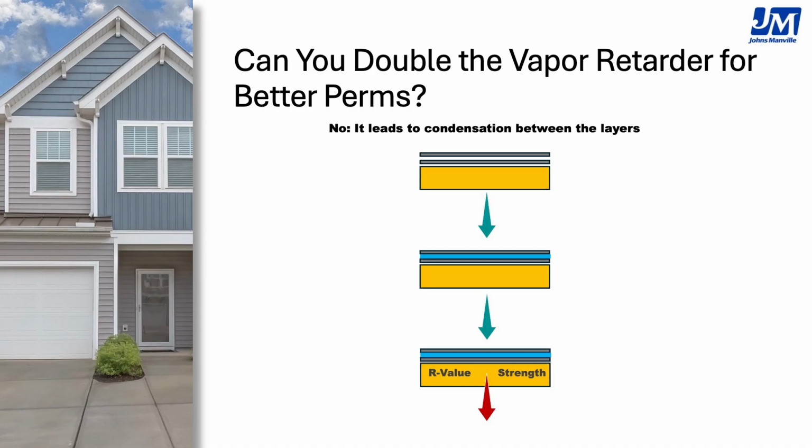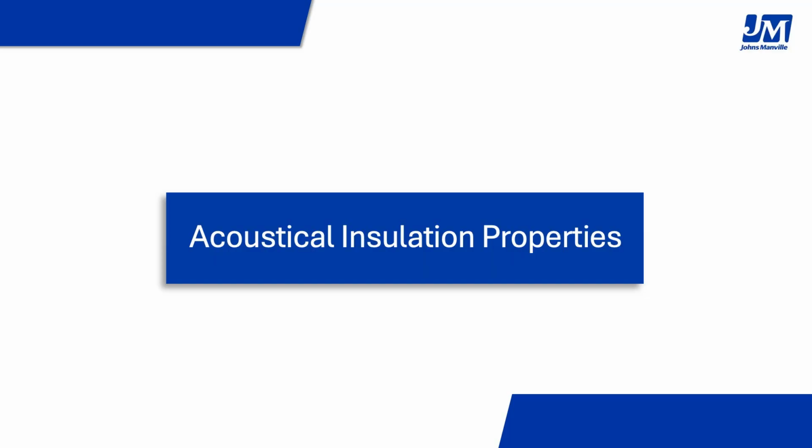I will tell you, you might look at something like this and think, well, what about polyiso foam? It's got foil facers on both sides. Isn't that a double vapor retarder? It's not, because that's a solid material, right? We're not going to get moisture building up inside there, because moisture won't go through any of that material. It's more like if we had foil facer, fiberglass, foil facer, that sort of combination is what we would not want. We've covered heat and moisture.